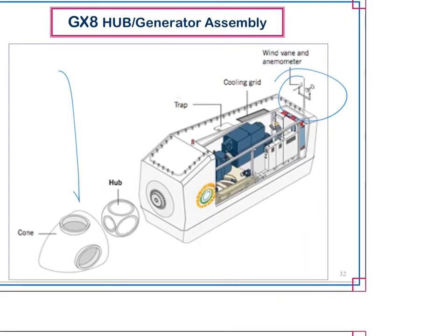So that's how we orient to the wind, and then again, you can get a sense of scale. You can get a look at the adult male, I believe it's a male, that is there. And then the standard stuff: you have to have warning lights for the FAA. I think anything in the US over 200 feet has to have a beacon at the top that's constantly blinking. You also want this part here, which is a lightning arrestor to protect some of the electronics. The blades themselves also have some equipment designed to take a lightning hit because they're made of fiberglass, but you still want to direct some of that energy away from the devices, and that works pretty well.